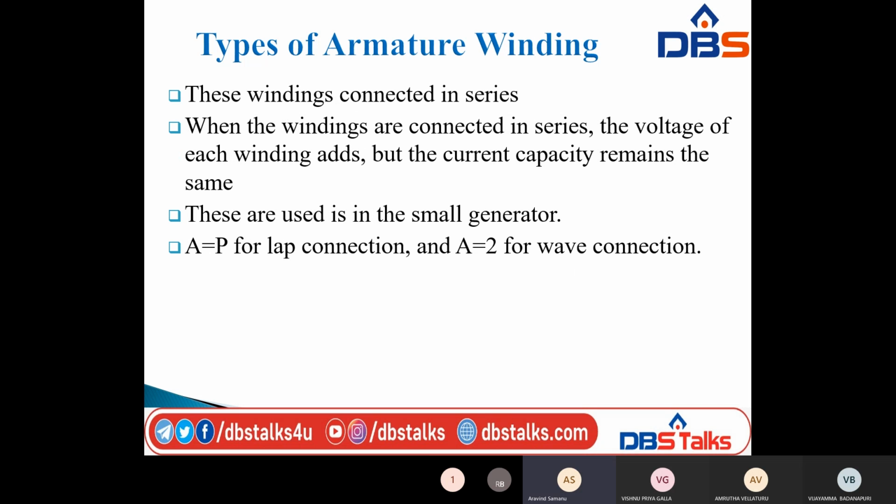So these windings are connected in series. In the previous lap winding, the windings are connected in parallel. So here in this case, the wave windings are connected in series.